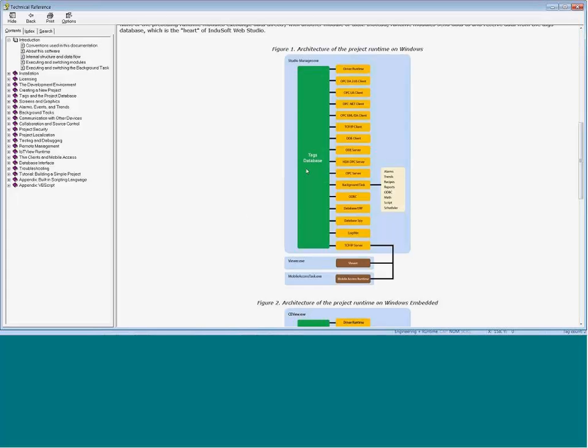We created a tag called temperature, and we were able through TCP/IP server, which opens up in the background, to view that on a couple of different screens. We were then able to change the slider, which wrote back to the tag database and then updated that. And then in this case, we were using the database SPY to either write it or read the value. Now what I'm going to do is add a driver in here. Notice that all the tags are basically internal tags. There's no concept of, is it a communications tag, is it an internal tag, an external tag?